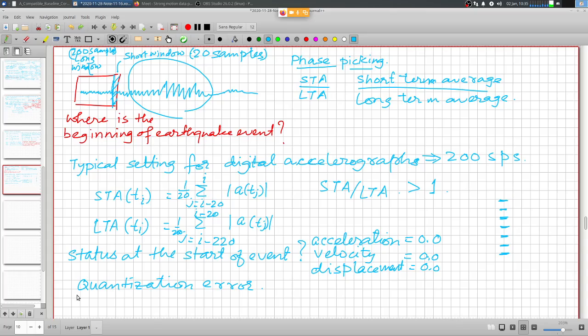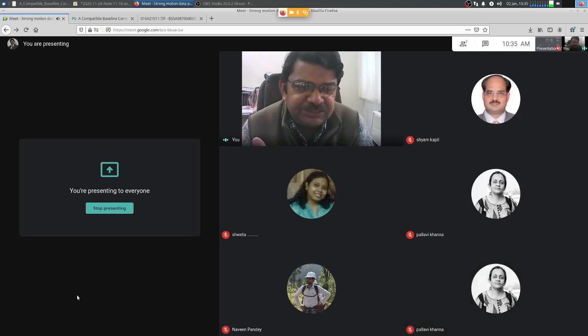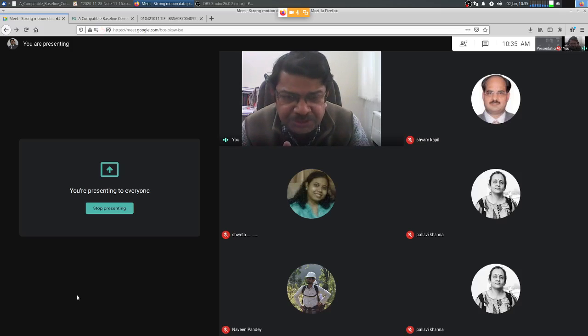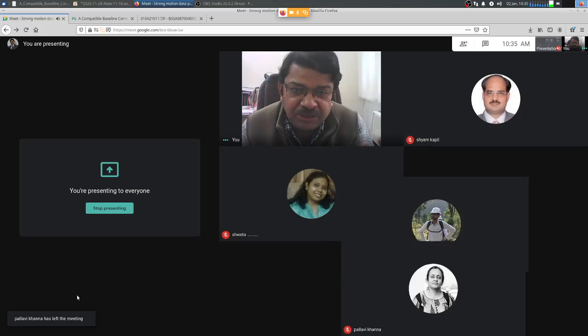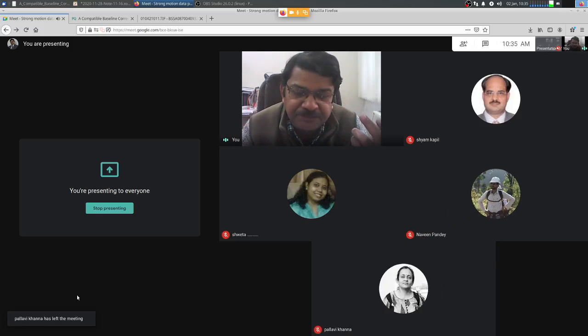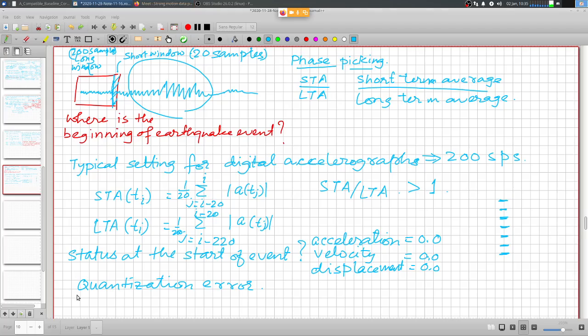that keeps on drifting away. Its null position. You might have observed this in various sensors that you deploy. Over a period of time, its null position shifts, and you need to keep on periodically adjusting the null position. That is referred to as DC offset. You can never be sure that there is no DC offset in the recording, and that DC offset is unavoidable.